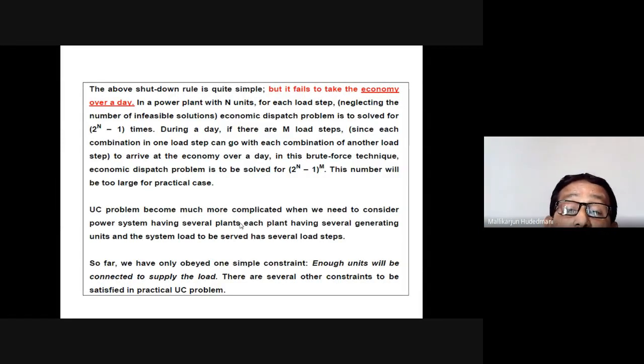This is how you maintain priority and evaluate the states one after another to find the cost effective sharing of generators in the commitment schedule. This is how the simple enumeration process takes place using the priority listing method inside. So priority is already there. Whichever machine you choose, the priority is by cost only. That is what is being taken.